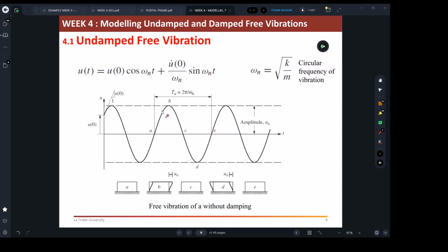This was also called T. It is actually the time it will take the building to travel from no earthquake, from static, all the way to the left, then all the way to the right, then come back to 0. That's the time period, the seconds. If you apply this formula, you will be able to find the natural frequency. So from the slide, just try to remember what T, the natural time period, and the natural frequency are, and understand the actual meaning of such parameters.